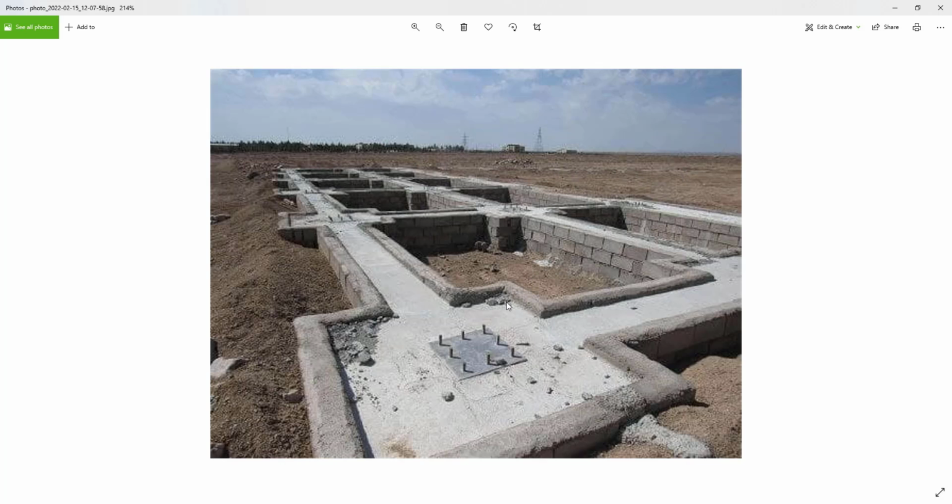So since we did our building path 1 meter down, we need to create, for example, sand locations in the middle of our isolated foundation too, because we cannot, for example, fill all of our building path with concrete. It's going to cost a lot, and it's not energy efficient. So we are going to use, for example, a combined footing foundation or a strip foundation.